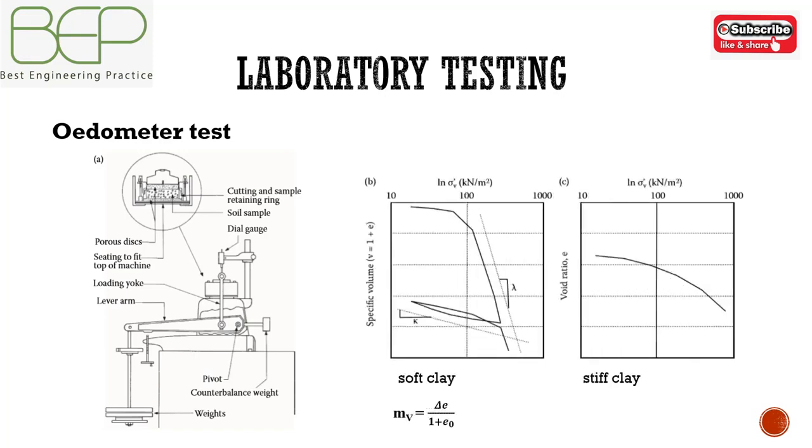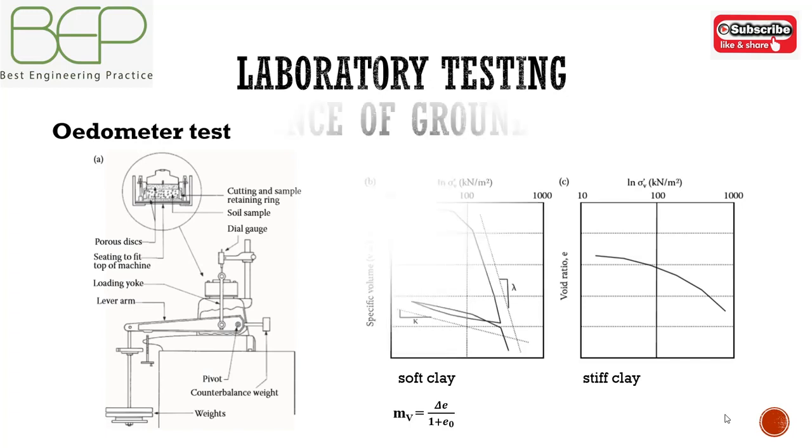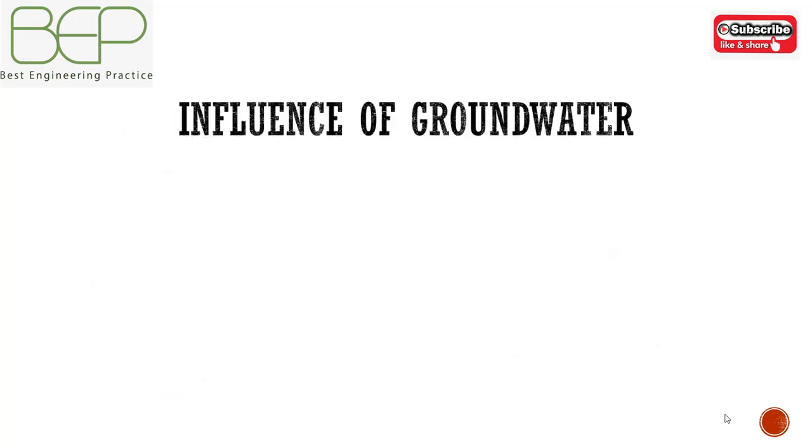For soft clay, the test is routinely used to estimate pre-consolidation pressure and the compressibility index. And small specimen height means that bedding effects will lead to a very significant underestimate of stiffness of stiff and very stiff clays. The loads on earth retaining structures are very significantly influenced by groundwater conditions.